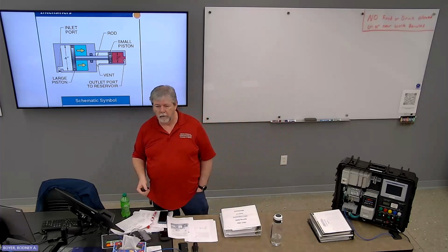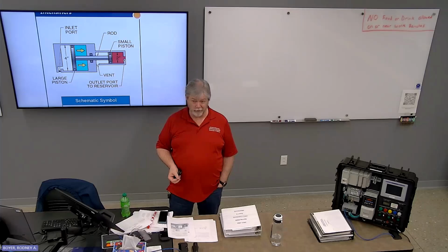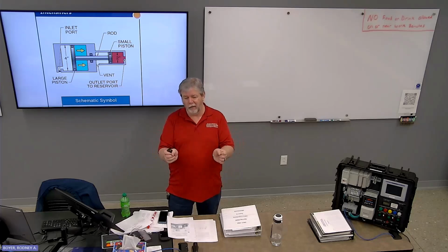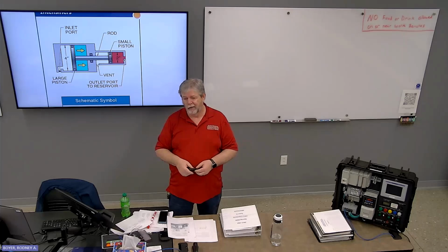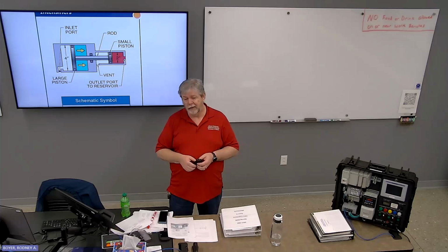What jobs can this thing be used for? Like, where would we need a lot of pressure in a small space? Well, it's not necessarily large pressure in small space, it's just large pressure. If you were going to use an intensifier to do the lock-in on a toggle press, your hydraulic system has to run at whatever set pressure, typically 5,000 psi.